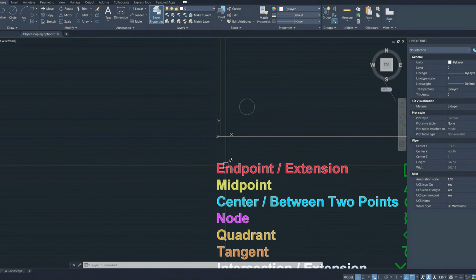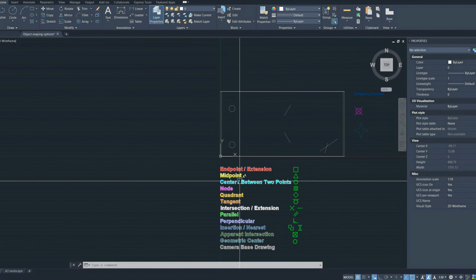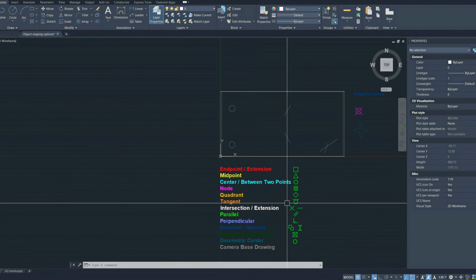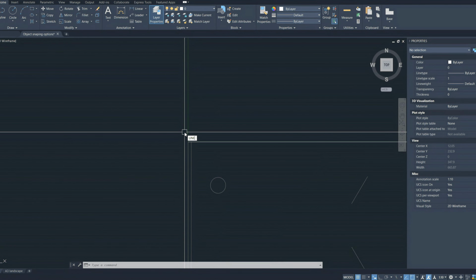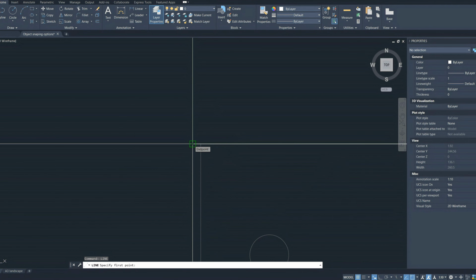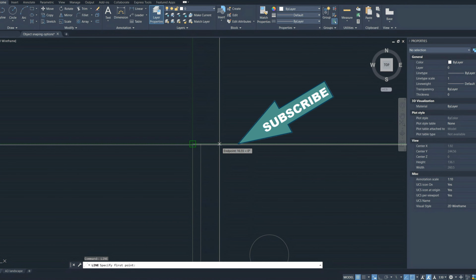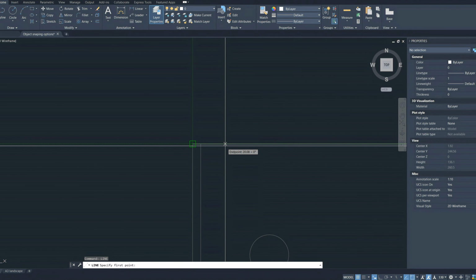This can also be activated with commands that are not turned on. That's why, for example, not all of my object snappings are turned on within this drawing, because it can get very busy and very confusing to see which points you're trying to snap to. We're going to use the endpoint again. So we're going to do a line command from this line here, and we're just going to track like we did earlier. We want to see that green line, as you can see there.